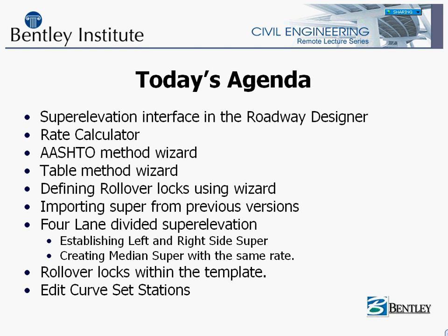We're going to cover it with a planar superelevation between the median and also creating a median super with the same rate as the left and right side travelways. Then we will discuss rollover locks and how they can be handled within the template. And then we will conclude with how to edit curve set stations within the superelevation portion of the designer.